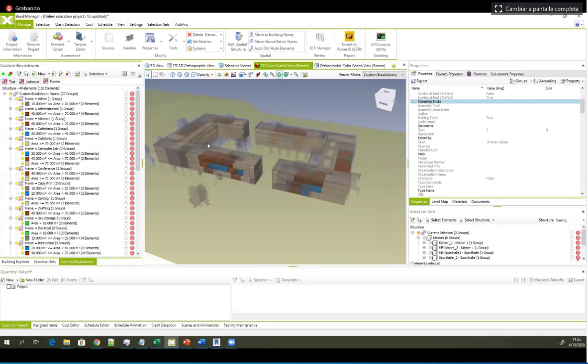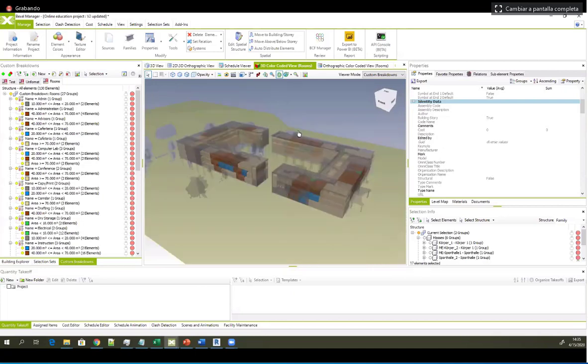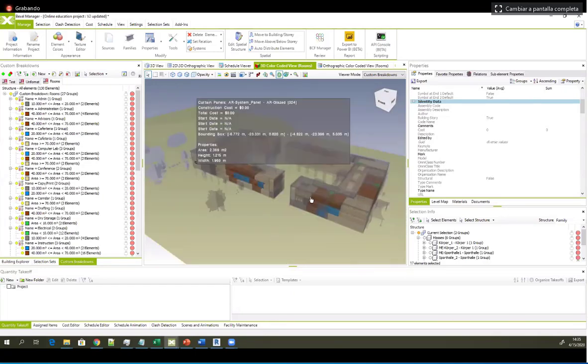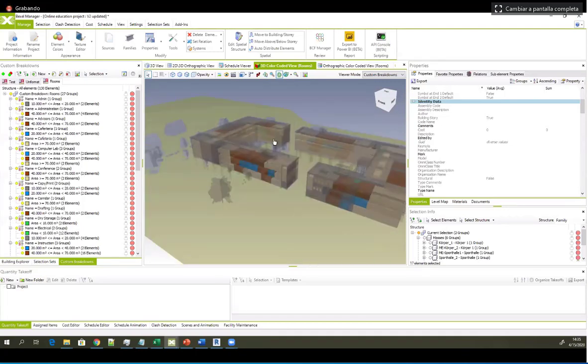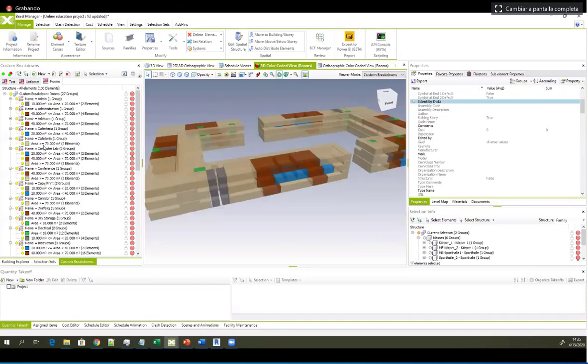And now the segregation according to the rooms is created, first according to the name of the building and then according to the area of the building. You may see that in the view, we see all the BIM model elements and colorized rooms. If you want to see only the elements which are included in your custom breakdown, you can use this small option right here, show only colored elements. So all the elements which are not rooms in this case will be excluded. So now we can see only the rooms which are colorized according to their values of area.